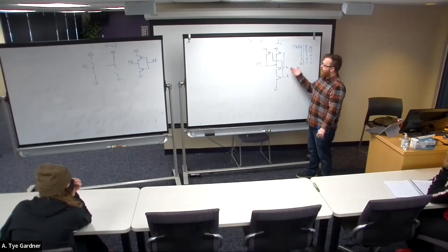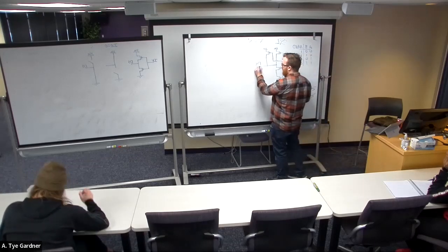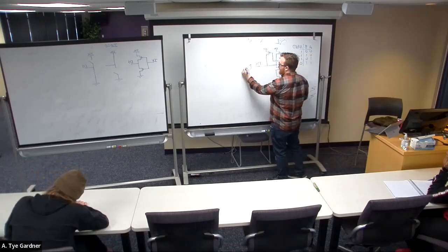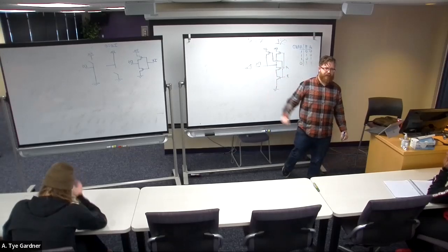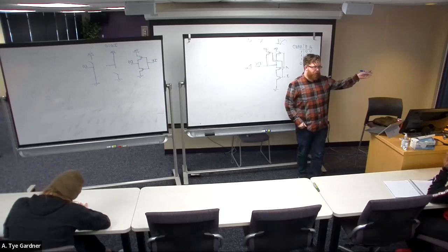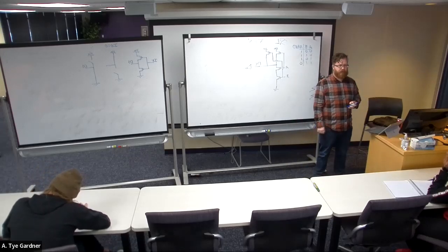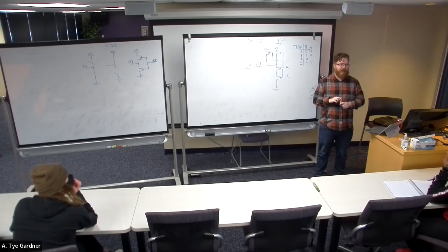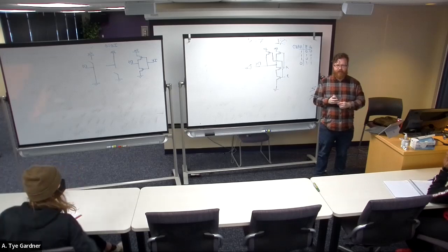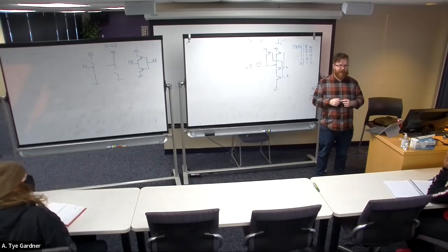Anyways, so in order to build an AND gate, I just plug this digital signal into an inverter, which we know is built like that. So in order to build a NAND gate, it takes me 4 devices. In order to build an AND gate, it takes me 6 devices. It is 50% larger to build an AND gate than it is to build a NAND gate.